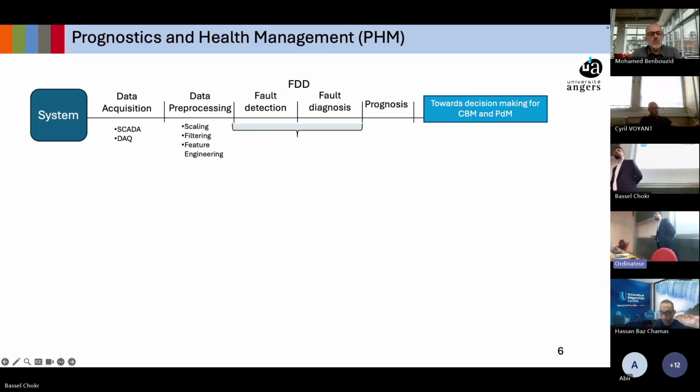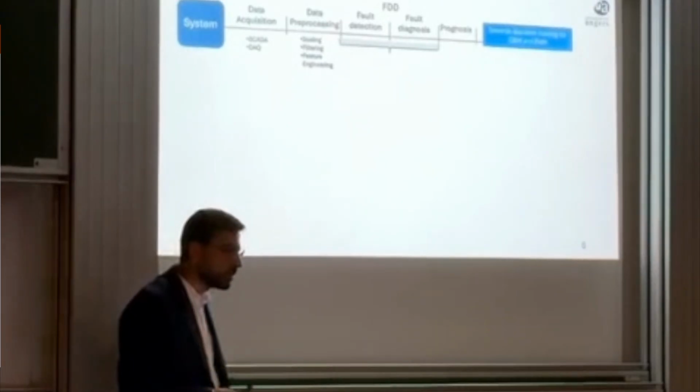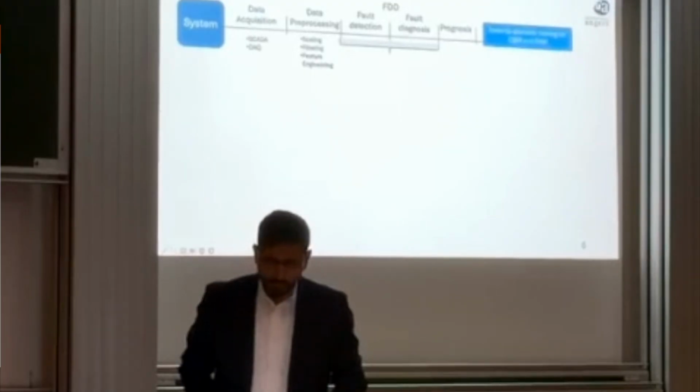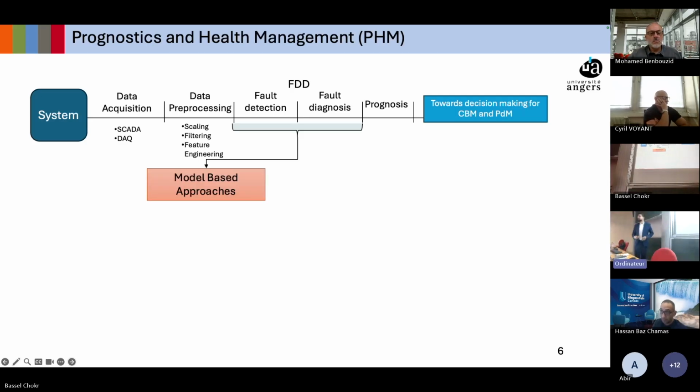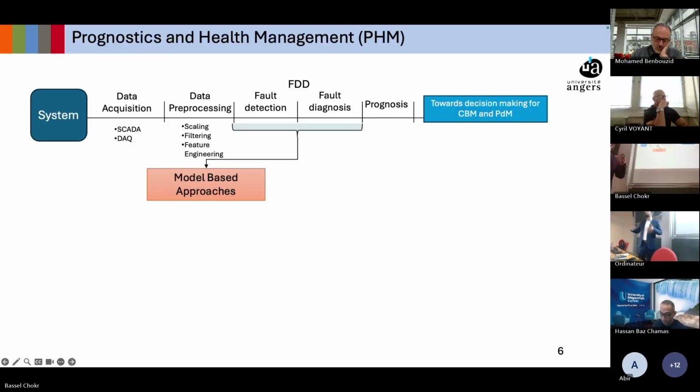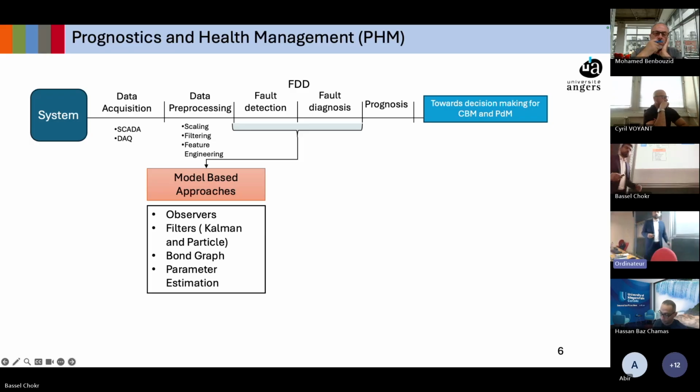predictive maintenance. Mainly our work will be under the CBM paradigm, condition-based maintenance, where, based on the knowledge that we have from the system, we can take actions. We will be focusing also, as the title of this thesis presents, on fault detection and diagnosis, FDD. The approaches go mostly in two directions. We have model-based approaches, where we could see observers, Kalman filters, for example, parameter estimation, and bond graphs, as in the work of Dr. Nizar earlier. This is a pathway that we could take.